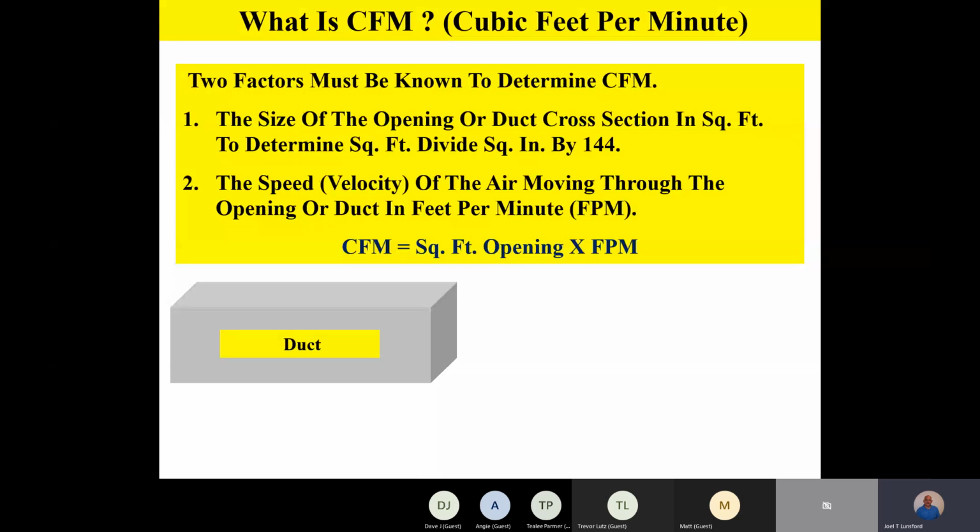If you dig deep enough in Manual D, you'll find that cooling coils, like evaporator coils on an air conditioning system, have a recommended velocity across that coil for it to work properly. The heat exchangers on a furnace are designed to have a given velocity of air going across them, and so on. As we start designing our duct system, we need to take into consideration the velocity of the air we're designing to as we move air through that duct system.